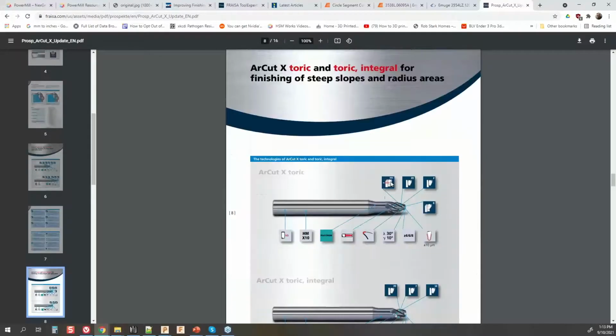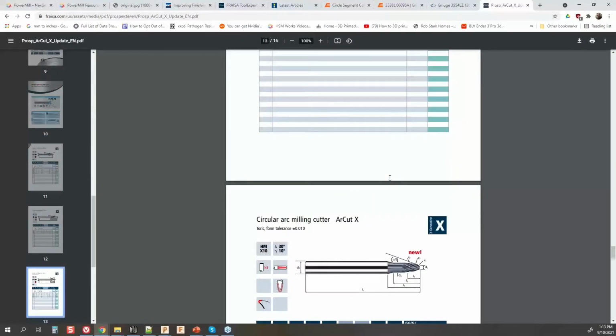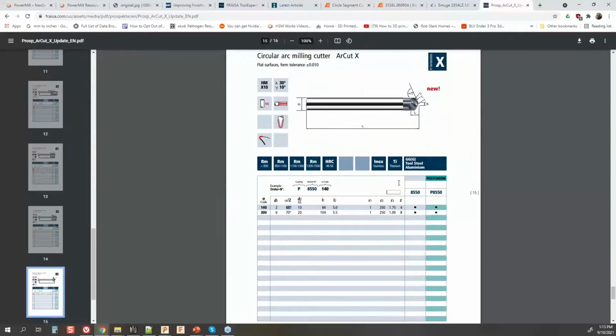I had this pulled up to a page, and as we go through the demonstration today, I'm going to show you what information I'm going to have to pull, both to create the cutter as well as to apply the most optimal engagement angle. So you can see in the image that I have from their PDF here, if I were to use this tip type tool and want to cut with the end of this radius, I need to know basically what that optimal radius that I want to cut with is, as well as the angle that it's going to be engaging on the surface. And that's basically primarily where you're going to get this information from. However, when you're in PowerMill or actually writing a program for it, these angles can change. Sometimes you need to use the opposite of the angle. We'll check that out once we get into PowerMill here in a moment.